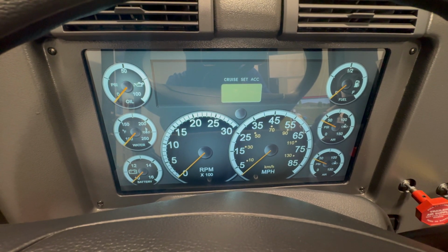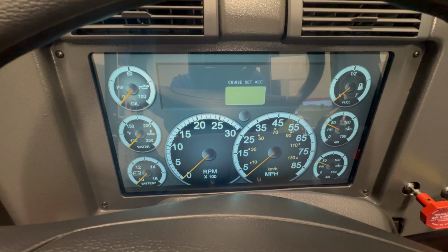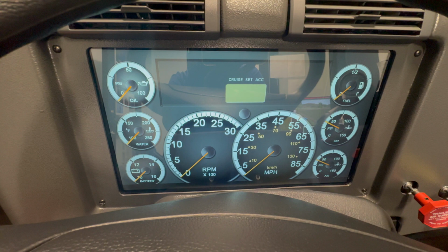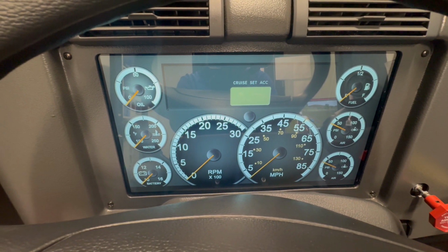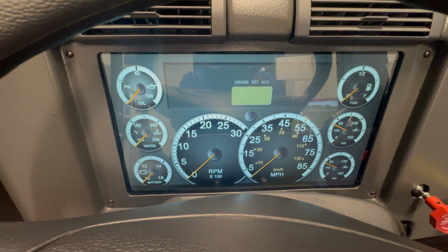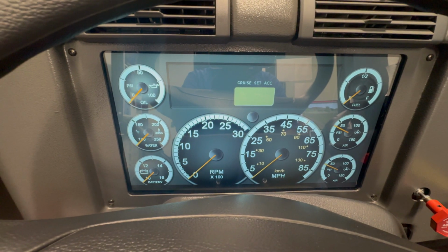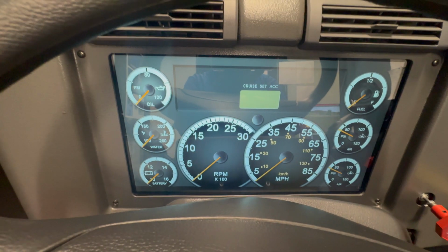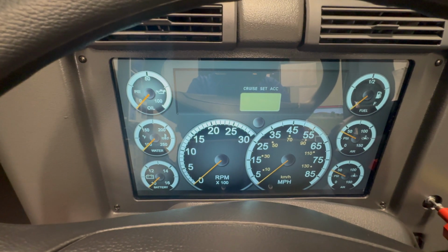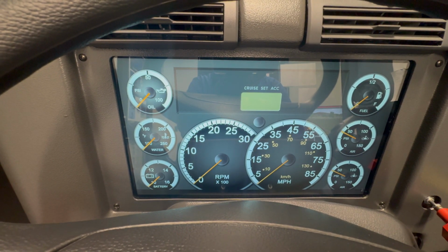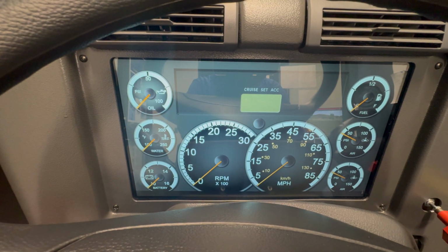It's just very, very basic understanding. And then, like I say, your RPM gauge is going to tell you when to shift, 12 to 13 to 1500 RPMs. Your miles per hour gauge is going to remind you of what gear you need to be in. And also your governor. You need to know when the governor is cutting out. When your engine speed governor, not the governor for the air compressor, but the engine speed governor.